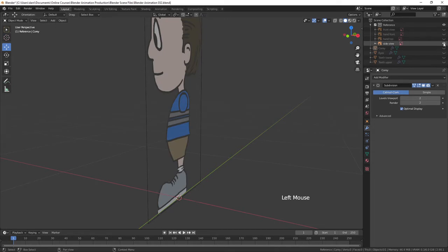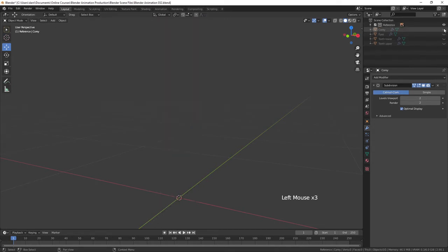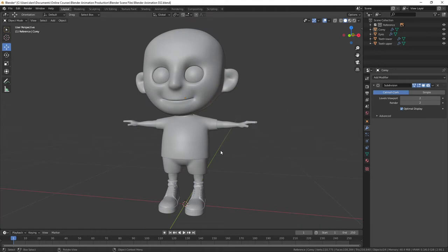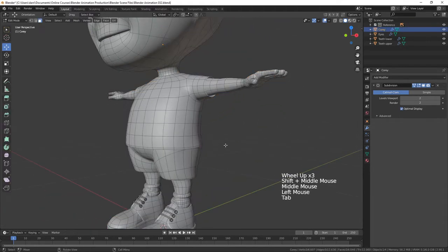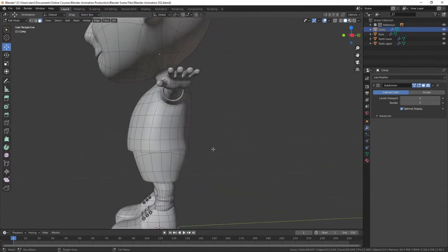And a good way to think about UV mapping is the idea of clothes, actually, where clothes begin as two-dimensional objects, as pieces of fabric. And they are assembled into a three-dimensional garment by sewing together seams. So what we can do here is simulate the placement of seams in the clothing to pull these pieces apart and lay them out flat in the UV editor. And that's really all UV mapping is doing, just cutting the 3D model apart and laying it flat so we can then apply two-dimensional textures.